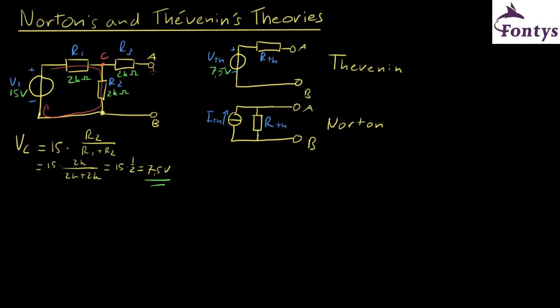So if you would put an ammeter in between, it will give a certain value, for example, 2 amps, 500 milliamps, whatever. So these two points are connected, and the current that is flowing from A to B is the Thevenin current, also known as the short circuit current, when you short circuit the output.